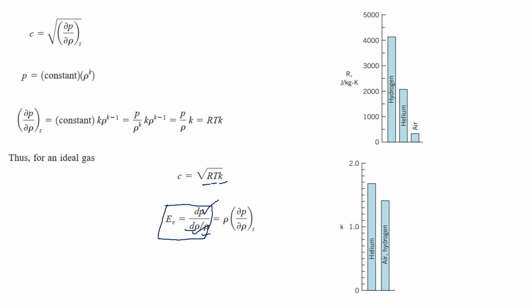So this can be further written in this form, and we can again write the speed of sound equation in terms of the bulk modulus of compressibility, because it also deals with the compressibility of a fluid, that is, how much pressure is applied, and by that change in pressure, how much the fluid is compressed. So we can also see that the bulk modulus of compressibility with respect to the density can also be equal to the speed of sound. And what does this equation tell us? This equation tells us that for fluids or anything that is not easy to compress, the speed of sound will be greater.